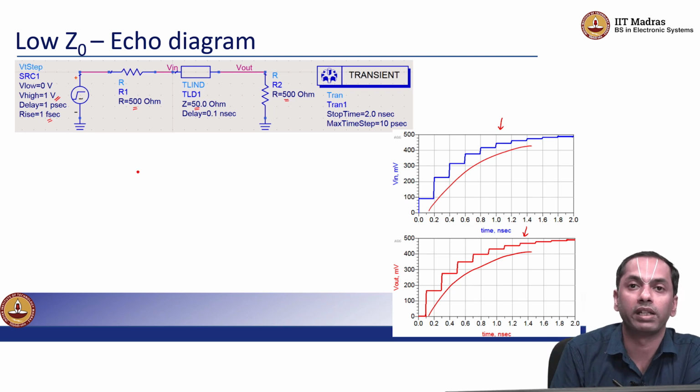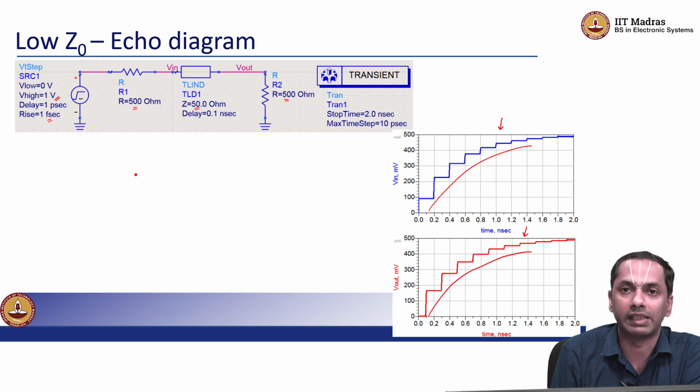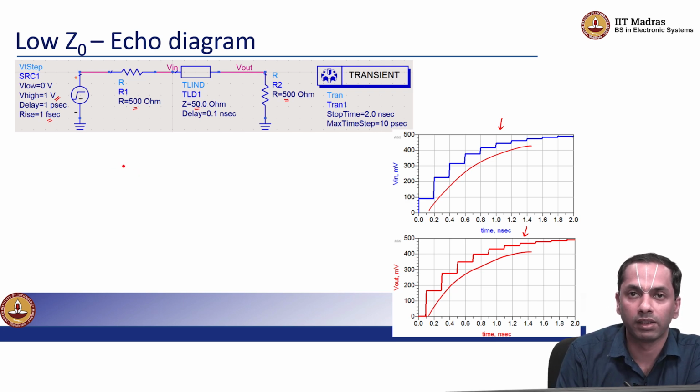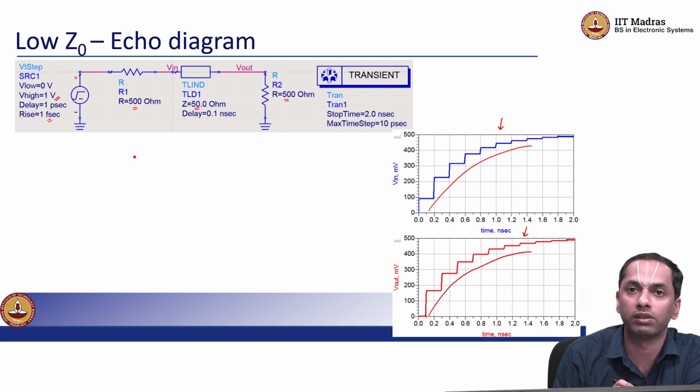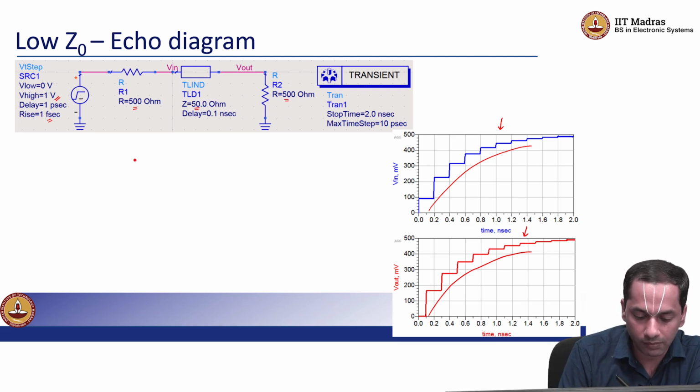So, we will go back to trying to model the transmission line using LCs. An ideal, lossless transmission line we said could be modeled as inductors and capacitors. Ideally, I would need a distributed model, but just to derive this intuition, I am going to look at a situation where I only have one LC network. So, I have my source, the transmission line begins here, and say one model for the transmission line.